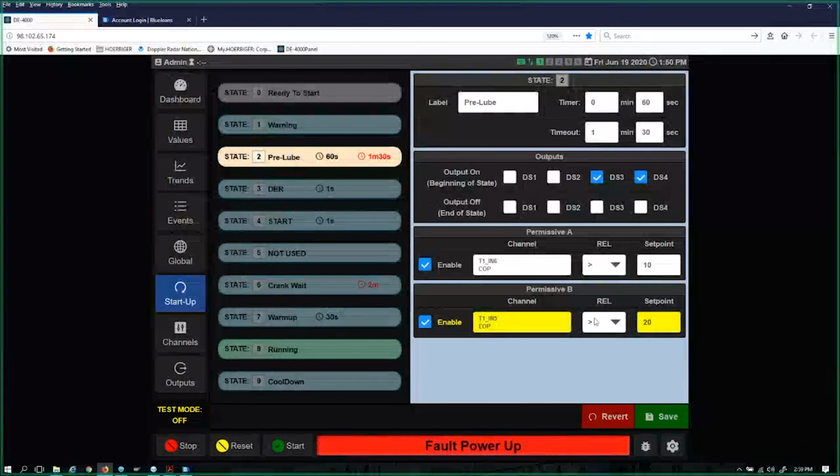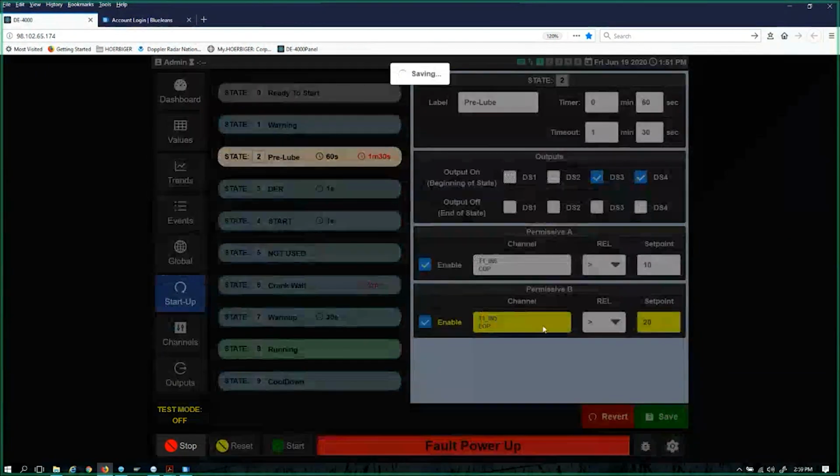And if you think about the old systems, we'd throw 5 relays in the panel and have one relay that blocked the next relay to cancel this out and that out just to make sure we got a preloop permissive. And with this system now, I'm able to eliminate all that. So no more wiring of LEDs, no more wiring multiple relays and making the panel overcomplicated. I like to do direct connections, and so that makes it really nice for me.